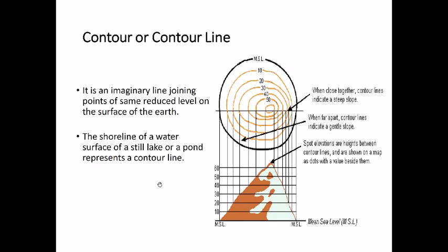Let's see over here. This picture represents it very accurately. Now we have a hill. If you take elevations along this part of the hill, you would draw this contour over here. Let's say this is for 60. All the points along this circumference, on all sides of the hill, make up a line of 60. Then if you do it over here, all the points along this are at 50.